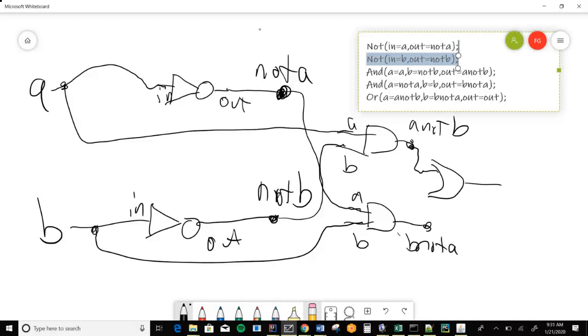So then this A equals A NOT B. And then my B input equals B NOT A. And then its out becomes the out for my circuit. Does that make more sense, Andre? Cool. So it can be fun to draw these, but it also winds up looking like a big pile of spaghetti pretty quickly, which is one reason why I think conceptually it's really cool to see that this is what the HDL is representing.